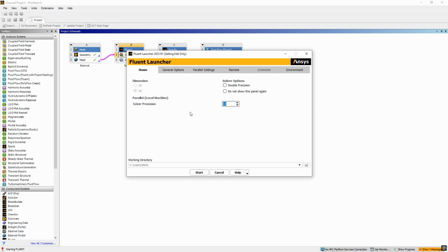And when we launch Ansys Fluent, if we are seeing certain errors, for example, it's not loading or you get this weird error, try reducing the number of CPU cores here and see if that works for you, because if it exceeds that value, you will get an error. It might say different things. It might say licensing error, it might say launcher error, and this is one solution. After doing all the settings, we can launch it by clicking start here.